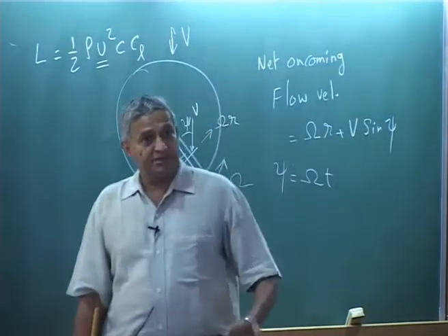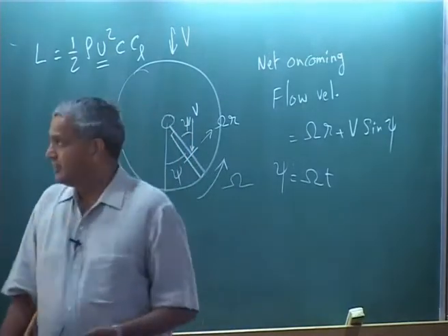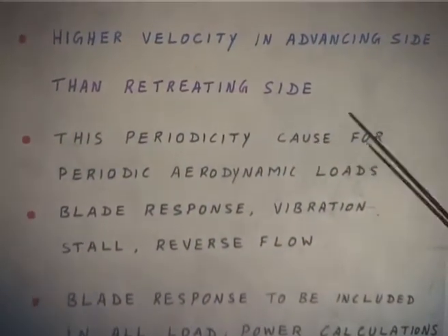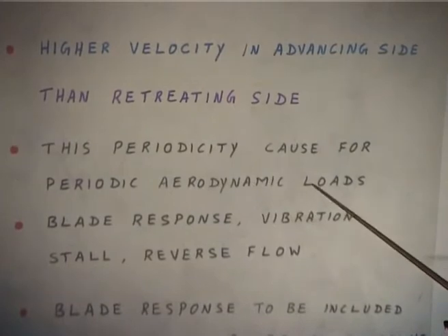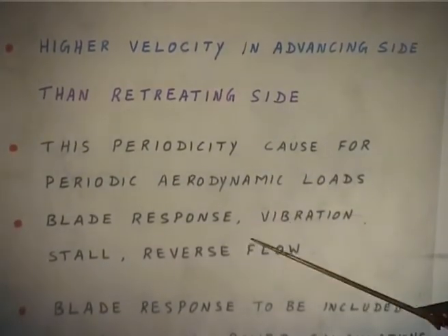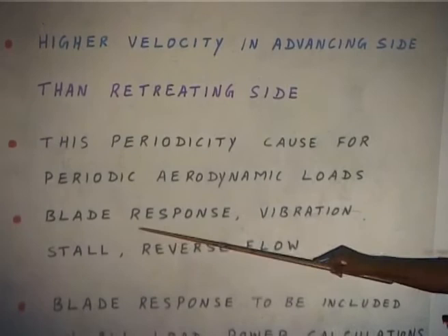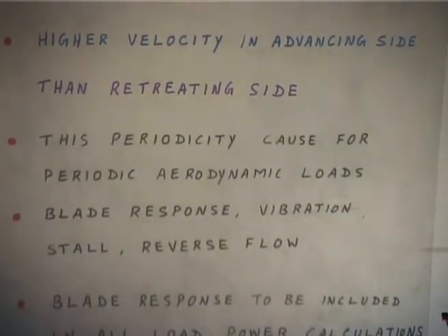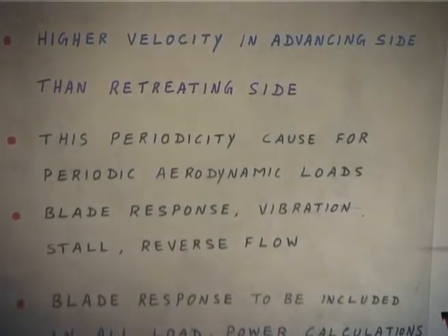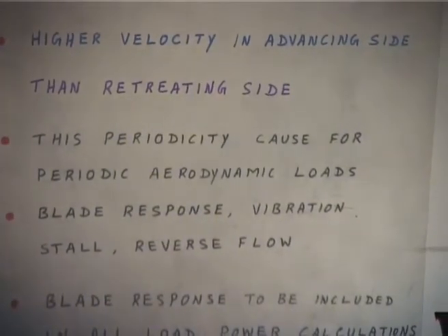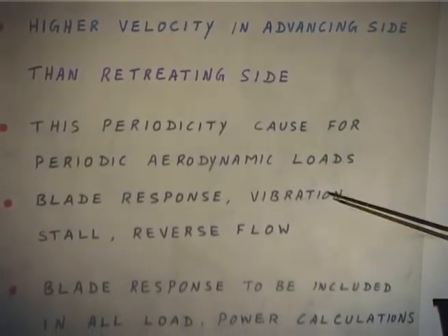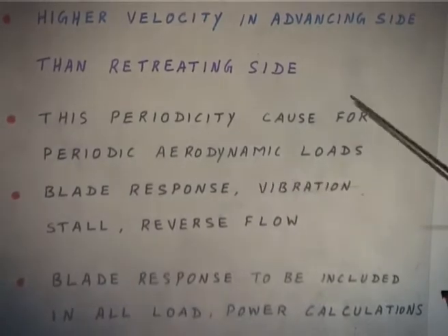The moment you have time varying quantities, that periodicity will cause periodic aerodynamic loads, and that will cause blade response, because you have a time varying load. A time varying load acting on a beam will make it vibrate. So, blade response is the cause of that, and this will cause vibration.